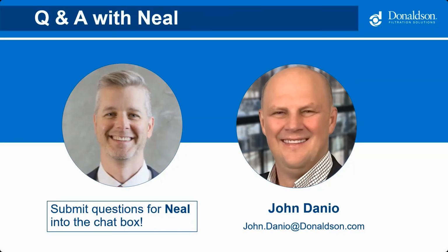And then more and more customers these days, especially on systems that are running anywhere from 10 to 24 hours a day, are going to put some form of VFD on the fan just to make sure that it's only pulling and using as much energy as it needs to. But if you've got multiple drops across the system and they're not all being used at the same time, blast gates are a great way to help keep things balanced.